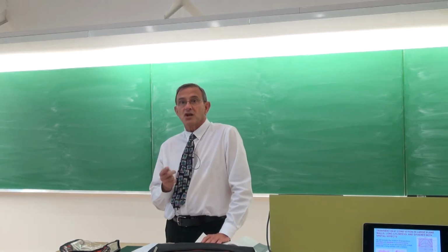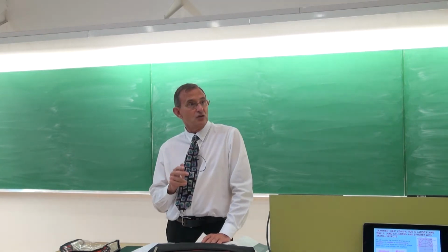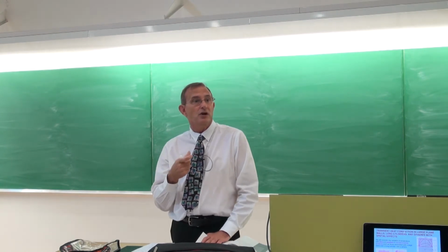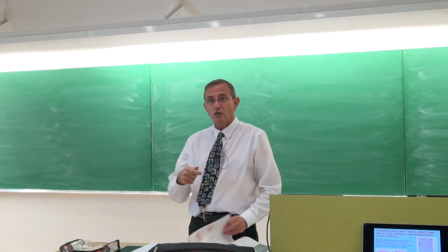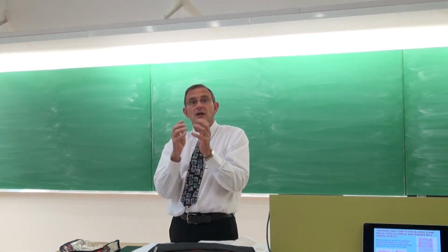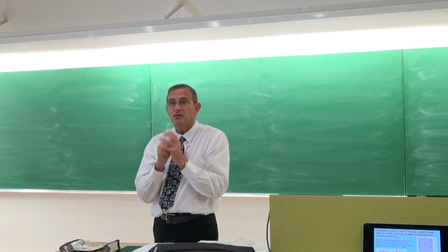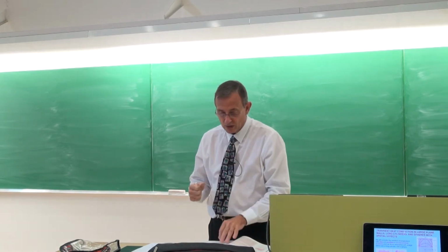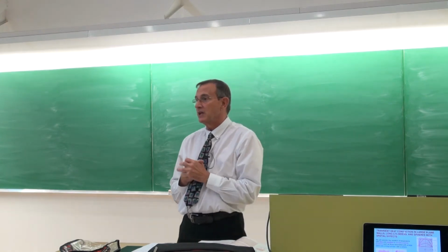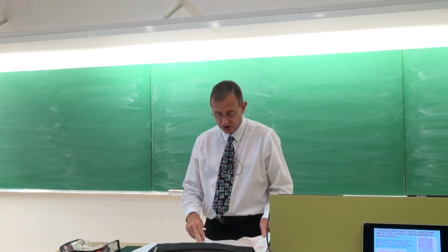And that is being prescribed by the Biot number. The Biot number gives us the ratio of the conduction resistance divided by the convection resistance. The convection is on the surface and it wants to go in, but how quickly it can go in is being determined by the resistance of the body itself. And if the Biot number is smaller than 0.1, then normally you will get a good approximation.